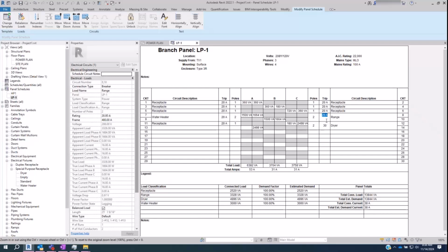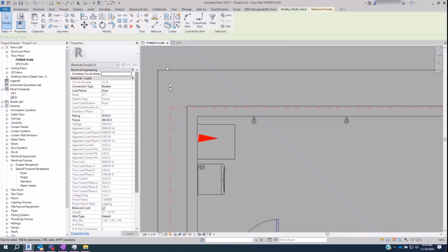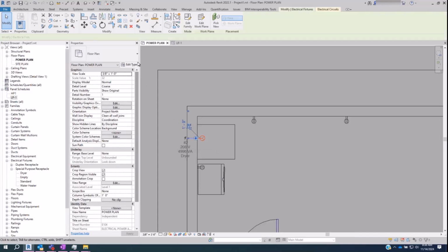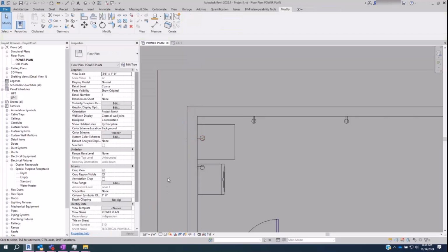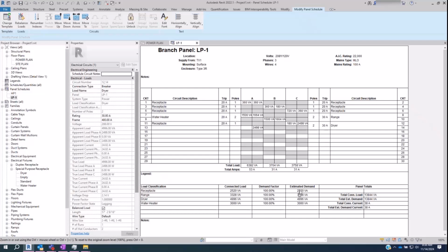Because I'm assuming we can't do that, will we just have to go up to the next size? That's a great question. The short answer is you don't have to go to the next size. We'll keep it simple. The NEC says you can. And since we're talking 0.04 of an amp, I'm not worried about it. We could totally use a 30 amp breaker. So yes, we'll just use a 30 amp breaker.